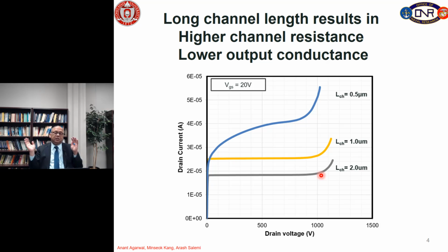So in power electronic circuits, there will be times when the device may accidentally get short circuited, meaning it will operate at the full voltage and full current. So you can imagine if you are sitting at 1000 volts and carrying the full current, there is a lot of heat dissipation, and that heat dissipation will destroy the device.